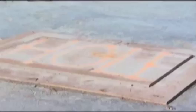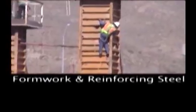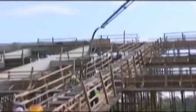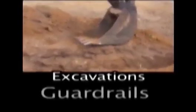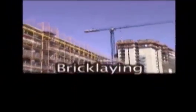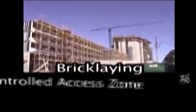Holes, including skylights, require the use of PFAS, covers, or guardrails. Formwork and reinforcing steel require the use of PFAS, safety net, or positioning device systems. Ramps, runways, and other walkways should be protected by guardrails. Excavations must be protected with guardrails, fences, barricades, or covers. Bricklaying and related work should have a guardrail, safety net, PFAS, or a controlled access zone.